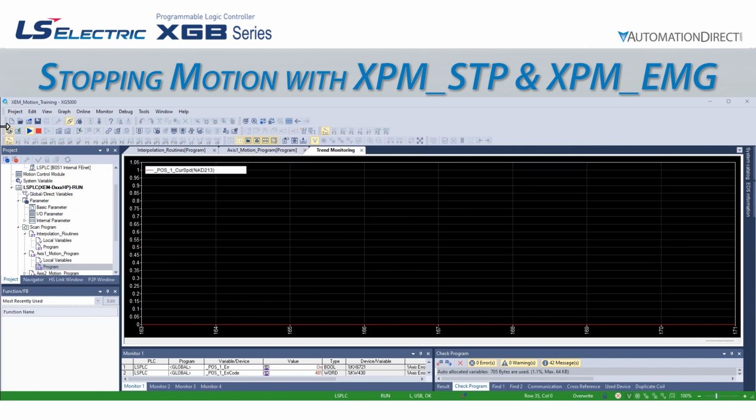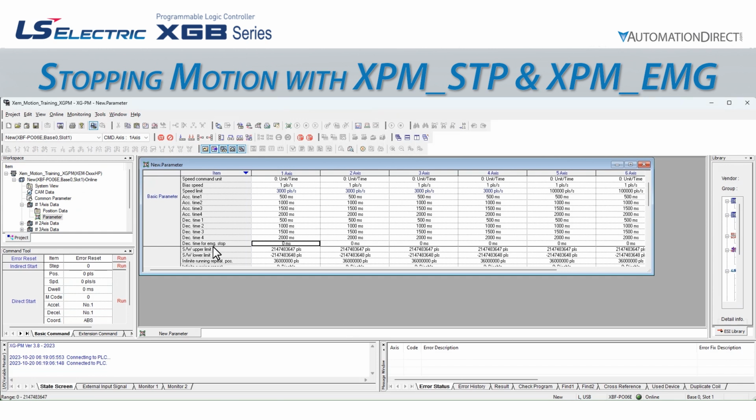Let's go out of monitor mode to stop the trend monitoring, and then go backwards on the trend. We see a nice hard stop when we triggered the emergency stop. Because the trend tool trends in 200 millisecond intervals, it appears to be a sharp angle downwards. In actuality, with our motion system at 0 millisecond emergency deceleration, we would have seen the axis jerk to a stop immediately.